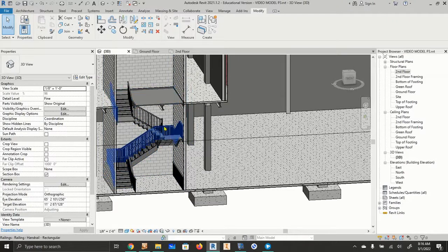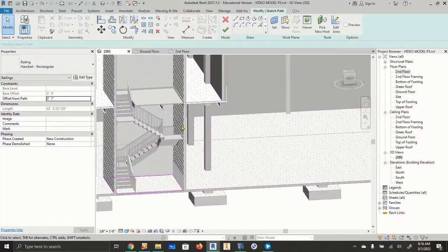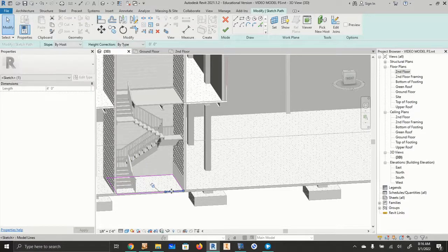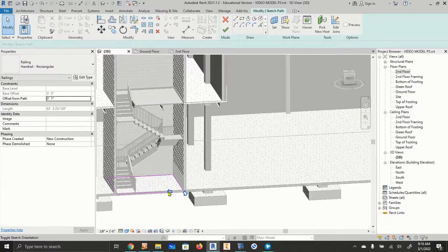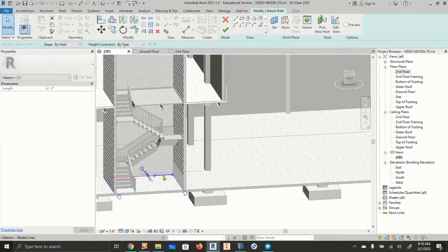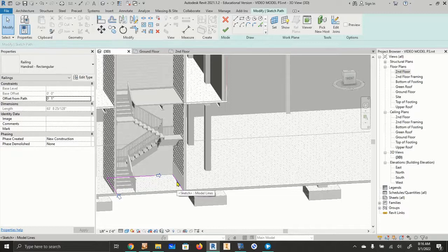All right, so next thing is we're going to look at this railing. This railing touches the outside wall. It's not really needed. So I'm going to double click that, and we're going to get into edit mode. Notice where it's editing. It's down here on the very bottom. And I'm just going to click everything on the outside and delete it because we don't need that. Anything that's on the inside here, we want to hang on to that. So I'm going to click on this and delete, and it's just going to be deleting those around until we get all the outsides deleted.